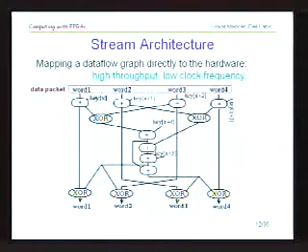And use very small arithmetic units that reduce the size of the circuit, and basically create a pipeline that is maybe 200 clock cycles deep. So for one data item to go through this pipeline, it takes about maybe 200 clock cycles. But then every following clock cycle, you get a data item out. So you get very high throughputs, and therefore very high performance if you look at the time it takes to encrypt, let's say, 1 megabyte of data.